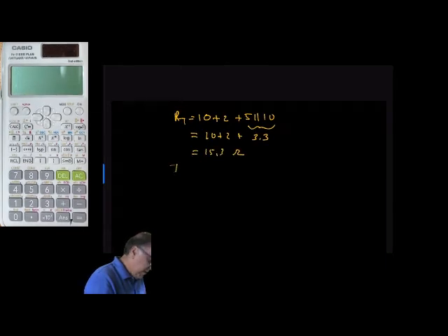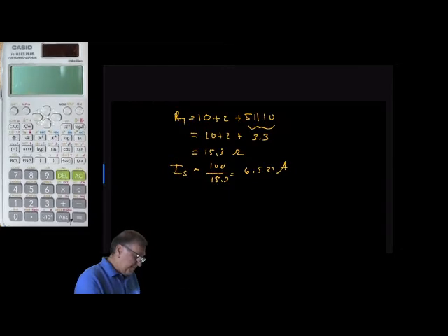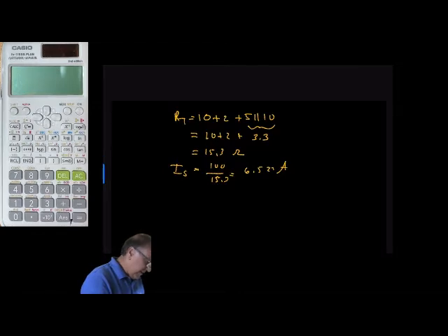So I sub S equals 100 volts over 15.3, which equals 6.522 amps. We could then simplify the circuit and it would look something like this. This becomes a current source of 6.52 amps.